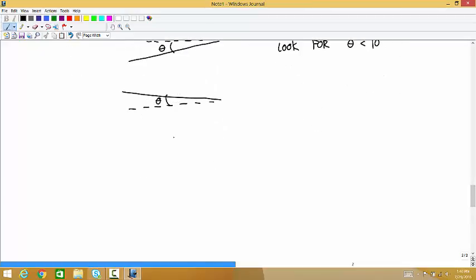It's that if you have a beam like this, here's one end and here's the other, you're going to get stresses that aren't just axial stresses when you put it into tension. The assumption that the only significant stress is an XX stress is not valid anymore, and that's going to mess up the results. So this is bad, the one on top is okay.